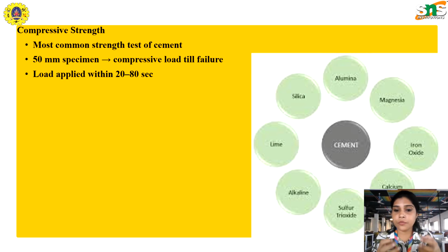In that cube shape, as time goes it will get set and strengthened, and it will form very hard cubes. So these cubes will be taken under compressive loads and we will measure how much load they can bear. Minimum strengths are prescribed for different grades, such as 33 MPa for 33 grade concrete after 28